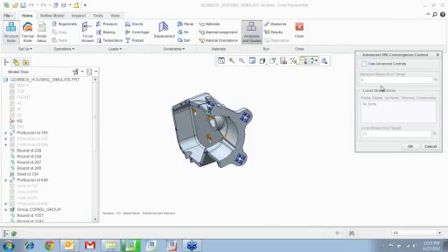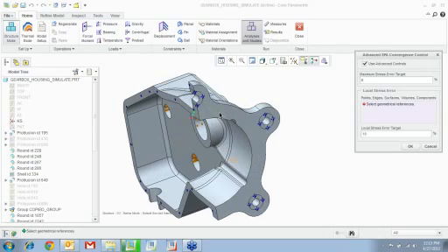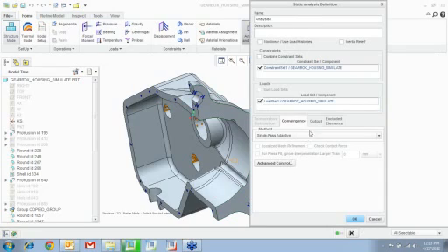Also in the advanced control, you can select a certain edge or a surface, right? So you can see points, edges, volumes, components. So I'm going to pick a surface and say, you know what, the maximum stress error is 8, but the local stress error over here, I want it to be 10. So if I know there is singularity, then I can choose to ignore it. Okay, so I can do these things with the advanced control.